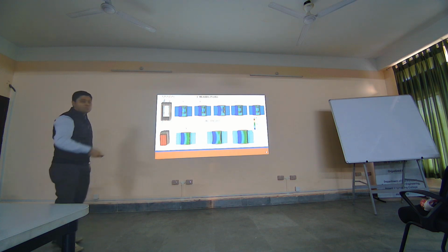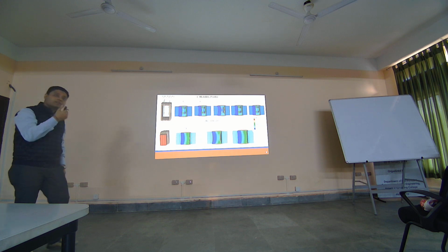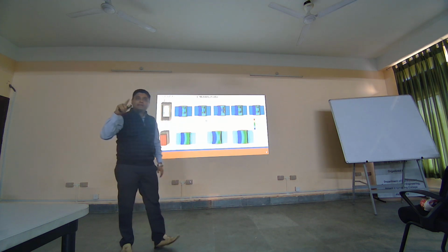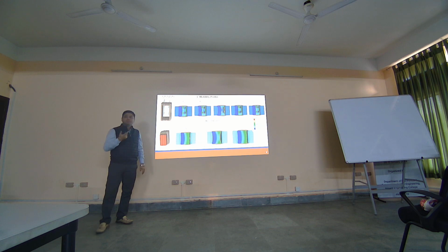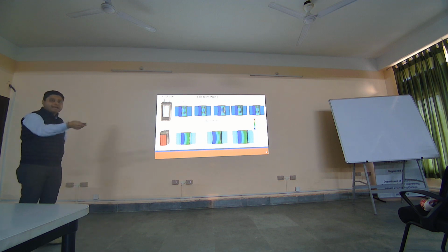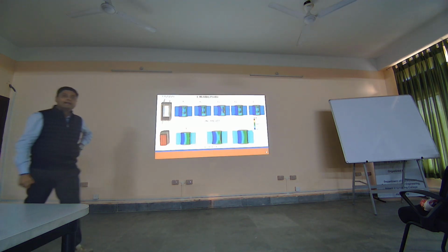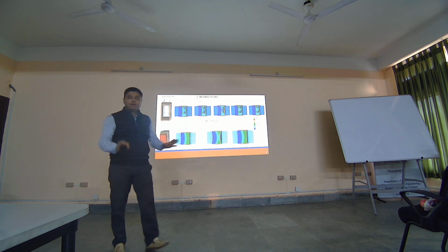So this is for electron mobility. The mobility also gets very well localized in those particular regions. Electric field localization and surface potential localization is okay, but mobility localization is an interesting revelation, because normally we do not talk about mobility localizations. So this is one of the things that we tried just randomly, and we found these things. Now the point is the possibilities where this thing can be used; we are still in the process.